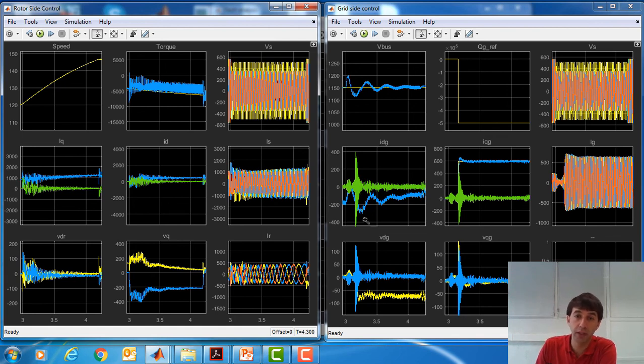So here the DC boost voltage oscillates, and due to the positive D component, these oscillations are damped and we have a proper operation of the grid side converter. Then here at second 3.15 we have the step demand of positive reactive current, which is given by the positive current loop. While the negative ones, D and Q, are controlled to 0.